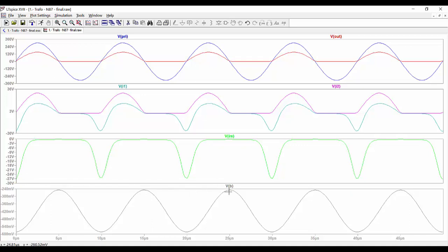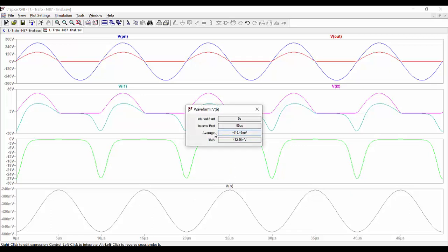Because here also we are showing the magnetic flux density, and we can see how we have a DC level in the magnetic flux density now due to the operation of the rectifier. We can check this. The average value is something like 416 millitesla. So we have a value which is well into the saturation region. We have material N87, which has the saturation region starting around 400 millitesla. And we are going beyond this point because here we are reaching almost 600 millitesla.